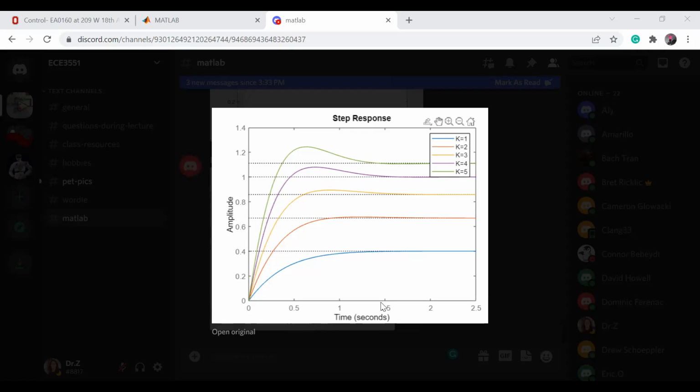Then do you remember what you should do to shift this to the left? Can someone remember? Just tell me, what do we have to do? You don't have to tell me exactly. So we want to change the settling time, make it faster. Do you remember how we would make our system faster? We worked on this, if you remember. What would be one way to do it? You remember we had the S-plane, and I identified omega d and sigma, and then I showed you those lines. So adding a pole to your system could do it. Remember, one of them was maybe to put a pole or shift the pole of the system farther from the line.